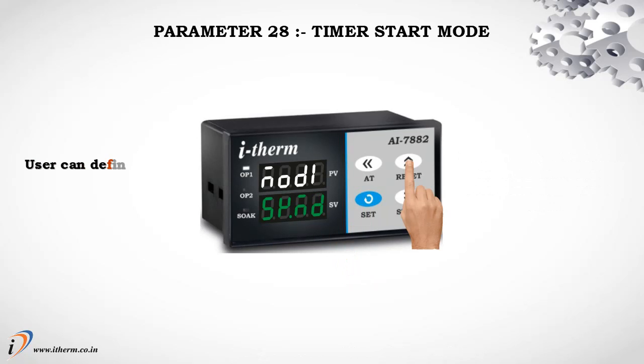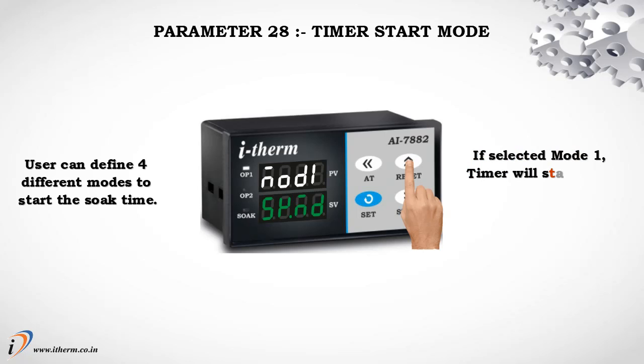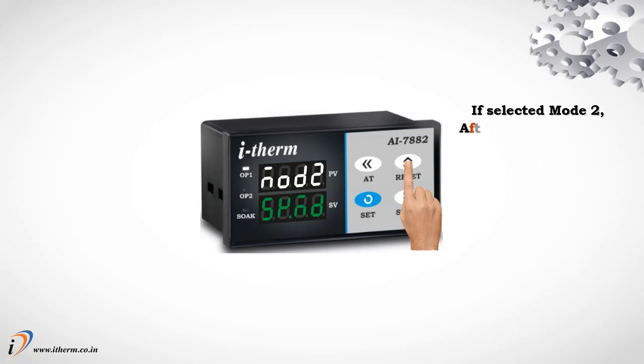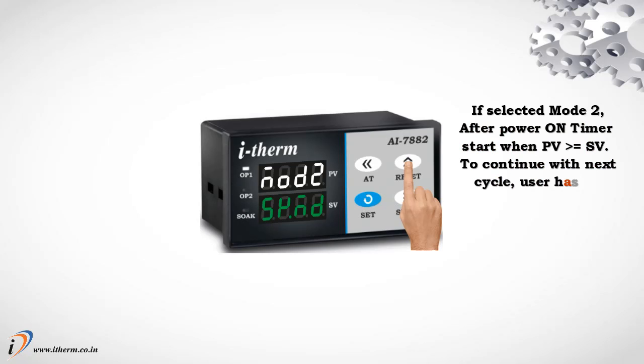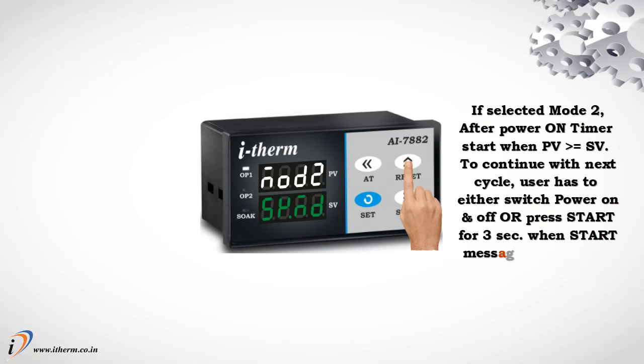Parameter 28, timer start mode. User can define 4 different modes to start the soak time. If selected mode 1, timer will start after pressing start key for 3 seconds, irrespective of process value. If selected mode 2, after power on, timer starts when process value is greater than and equal to set point value. To continue with next cycle, user has to either switch power on and off or press start for 3 seconds, when start message is displayed on the lower display.